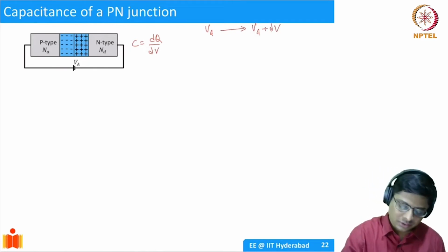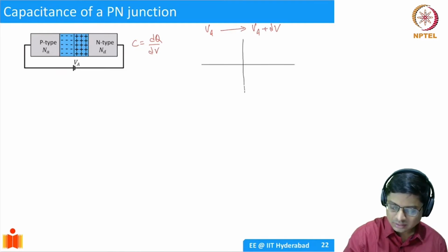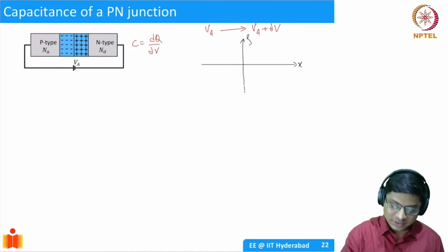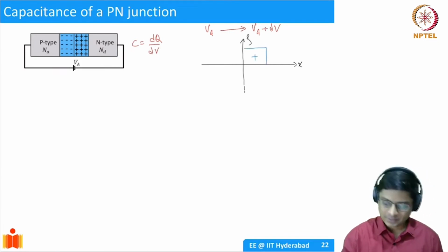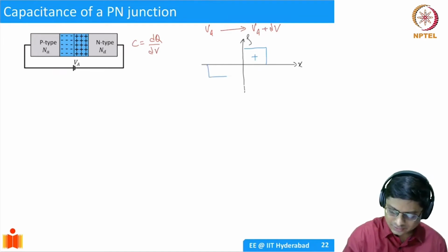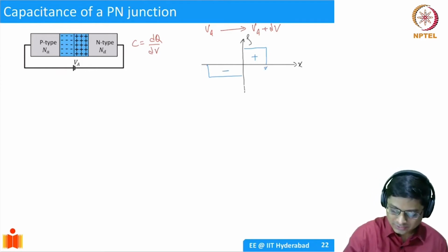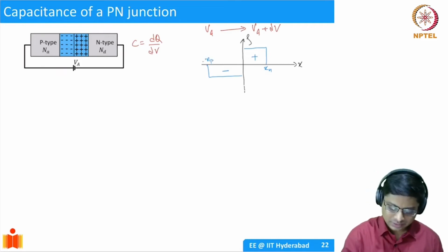Okay. So without all this, if you look at a PN junction, as a function of x you can plot rho. We have done it multiple times already. So what will we see in this situation? We'll see that there is a space charge in the N-type region, which is going to be positive, and there is a different width, negative space charge in the P-type semiconductor, and we call this xn and this minus xp. The junction is essentially x equal to 0. Right? This is 0.